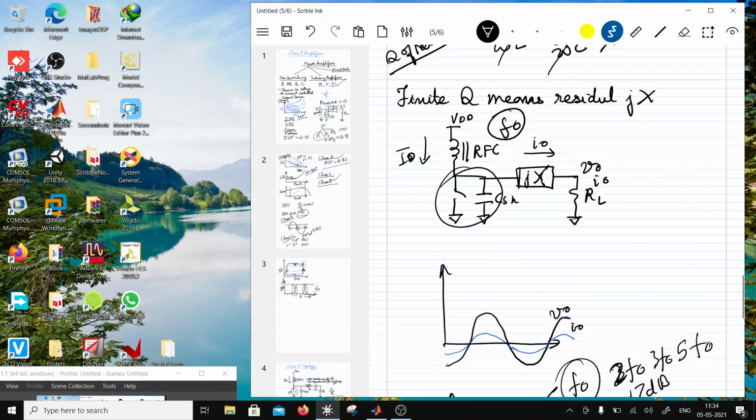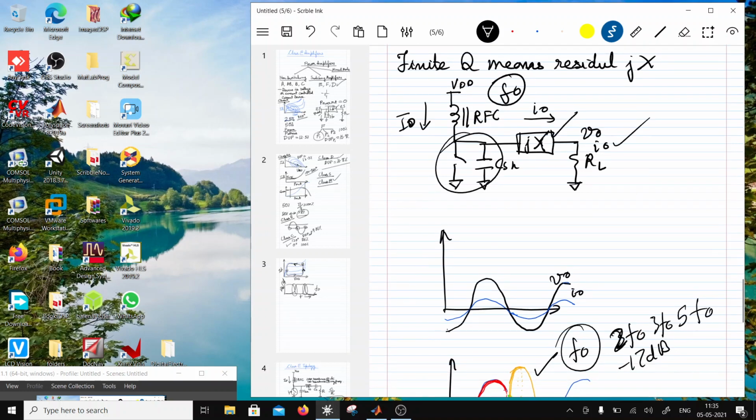So this waveform is basically having all the energy in the fundamental, right? And then what you do is you need this LC filter to filter the fundamental to the load, right? You are filtering the fundamental to the load using this LC filter. So I can say that this L and C combination is going to trap all the voltage harmonics, while this combination is going to trap all the current harmonics.